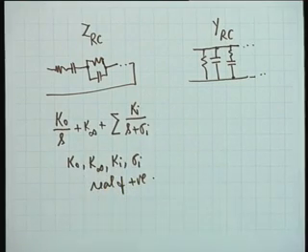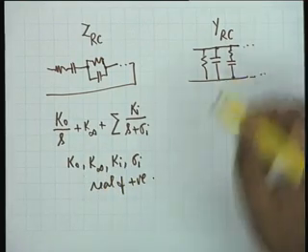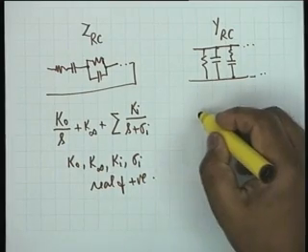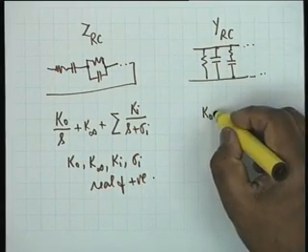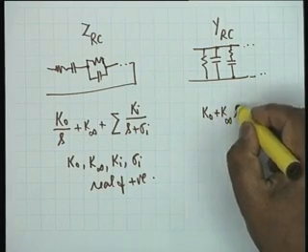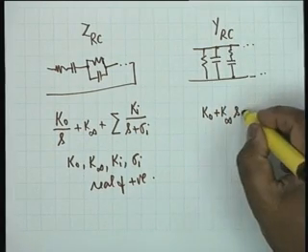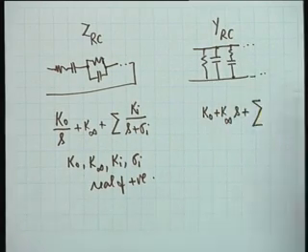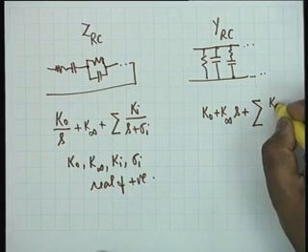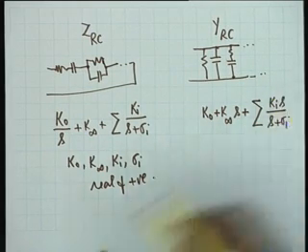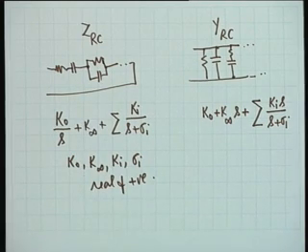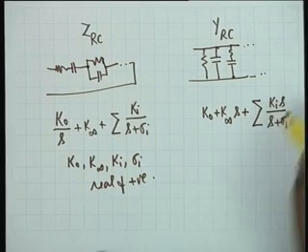and therefore all these coefficients K infinity, Ki and sigma I, they are real and positive. On the other hand, when we took an RC admittance, we saw that it is of the form K0 because of this resistance plus K infinity S because of this capacitor plus summation of terms like Kis divided by S plus sigma I. This is the difference that occurs in S here, because R and C in series, if you take the admittance, their admittance is of this form.